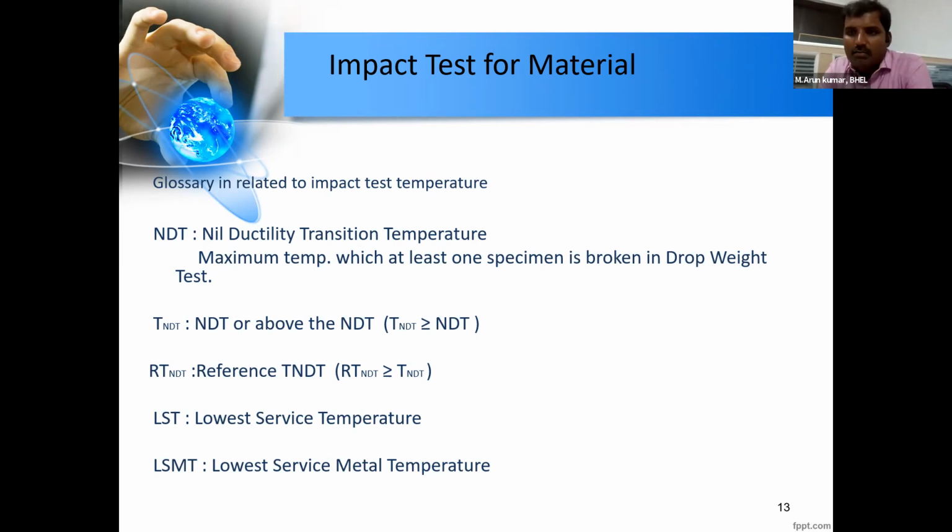That is called the raw material test coupon. That test coupon undergoes all the processes which the original job undergoes. For example, we are manufacturing a steam generator. That particular raw material is going to undergo two to three heat treatment cycles. So this coupon is also heat treated along with the job. Then once again, we establish this RTNDT.